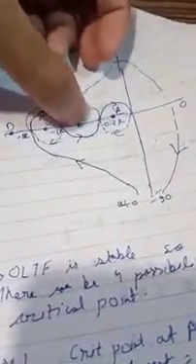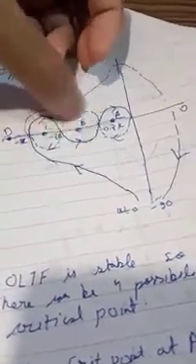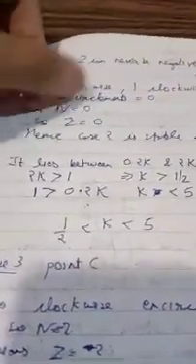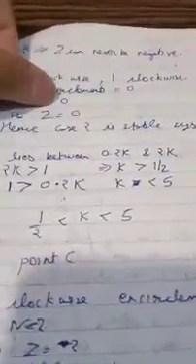So I take case 2. In case 2, there are one anti-clockwise encirclement and one clockwise encirclement. This small circle, for case 2, this point is B. Then minus 1 plus j0 critical point lies here. So there is one anti-clockwise encirclement and one clockwise encirclement. So the total number of encirclement will be 0 because one is clockwise and one is anti-clockwise. So it means n is equal to 0. So if n is equal to 0, p is equal to 0, so z equal to 0. So the case 2 denotes the stable system.